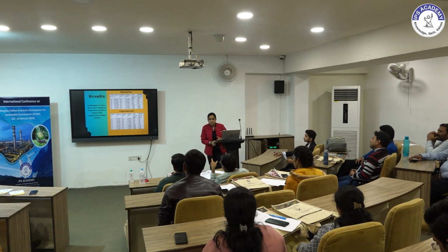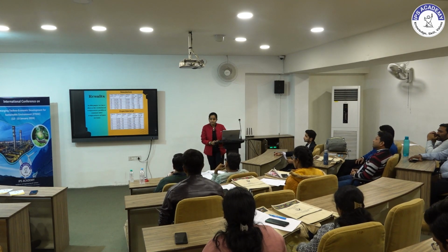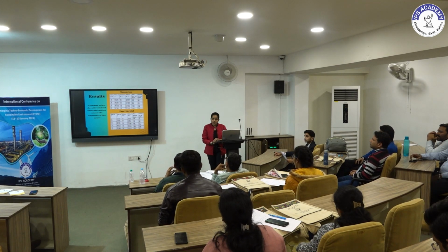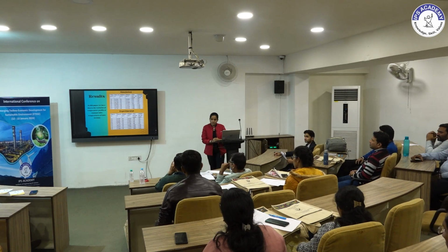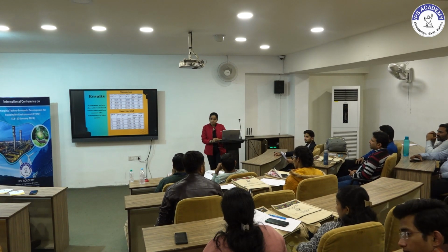Water in at 10 degrees centigrade. You did this in the lab. So what was the inlet temperature? 10 degrees centigrade, because there is a digital thermometer. So how did you maintain the temperature at 10 degrees centigrade? You have to circulate the cooling water. You supplied cooling water, meaning before feeding, the water was maintained at 10 degrees centigrade. Absolutely.